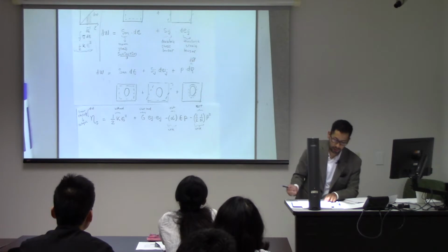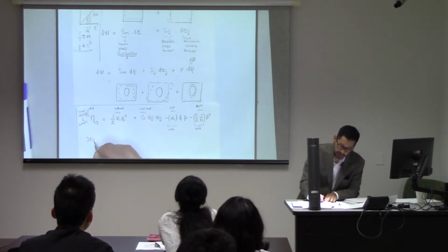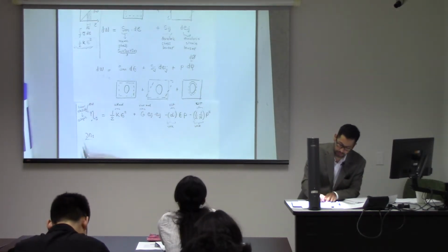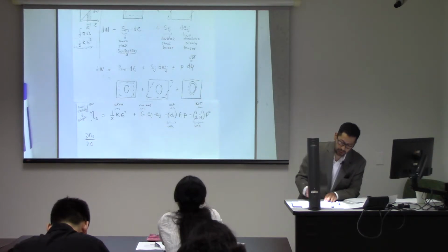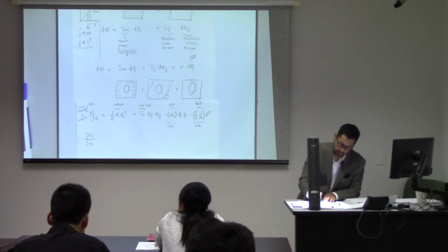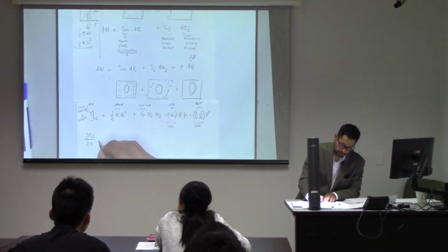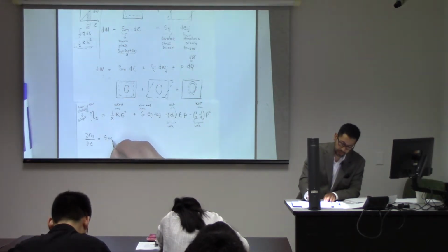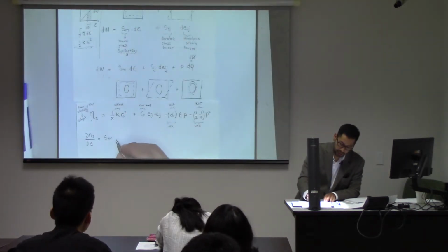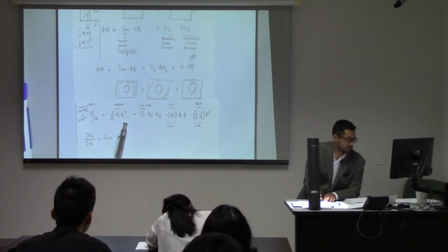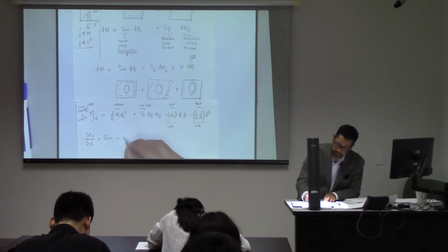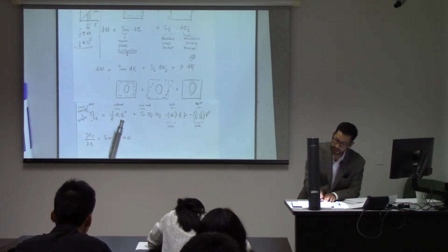So similarly, if I take the partial derivative of this free energy of the solid function with respect to the volumetric bulk strain, I'm going to get the mean stress, which comes from over here, and that mean stress is going to be equal, according to this equation that I have written over here, to K e, the derivative of that with respect to that one.